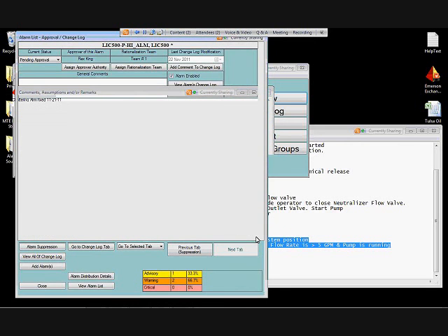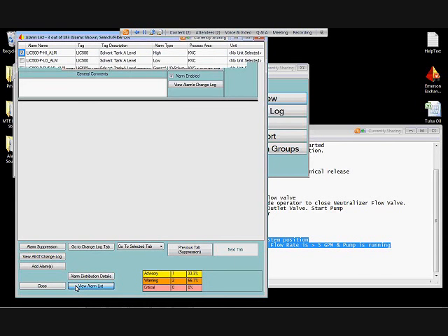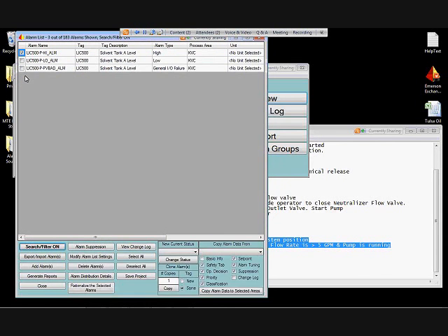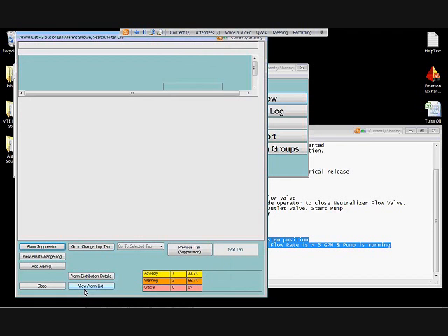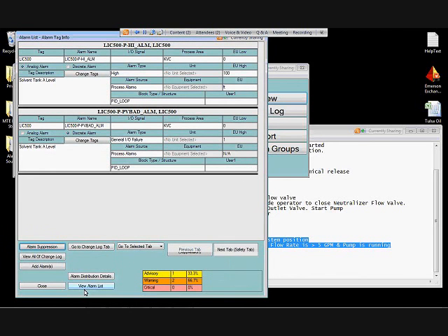So that's now recorded. It's pending approval because we still need to go through our MOC board and our MOC process to make sure that these changes are authorized. But now let's rationalize the PV bad alarm. This is a diagnostic alarm. So let's just jump right to the prioritization tab because that's what we need to do for this alarm.